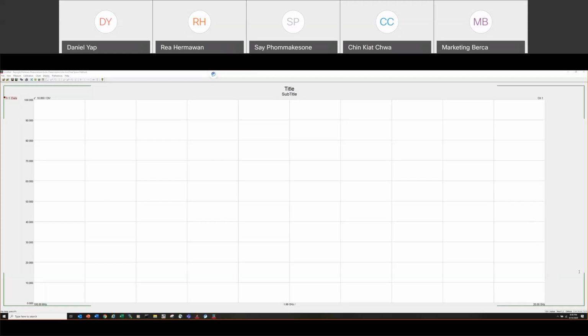Yes, I designed the sample to fit the waveguide, and I need to measure both mu and epsilon. Yes, if you can get your sample inside the waveguide, then you can measure mu and epsilon using the Nicolson-Ross model. It is the first model on top when you select define measurement in the software.